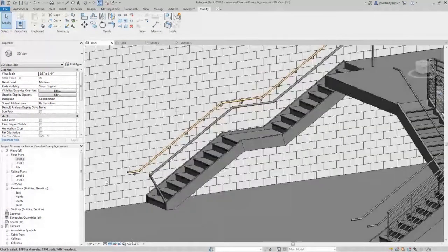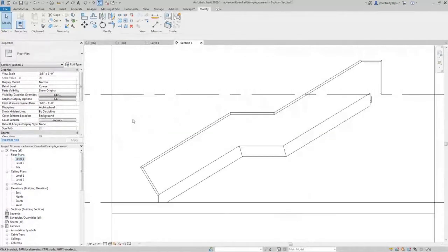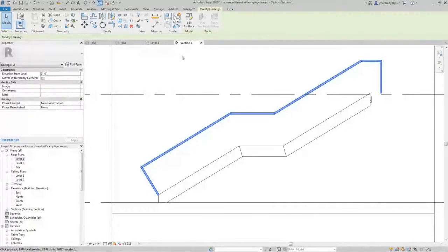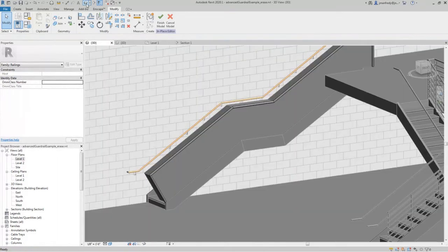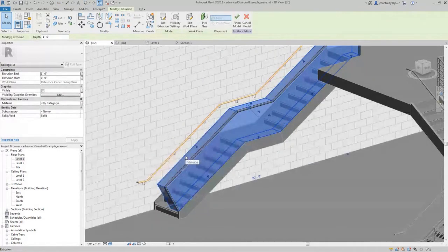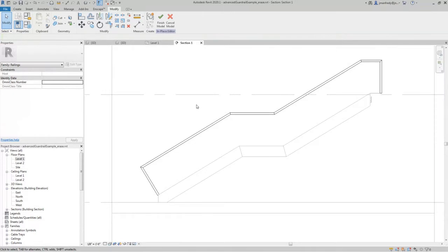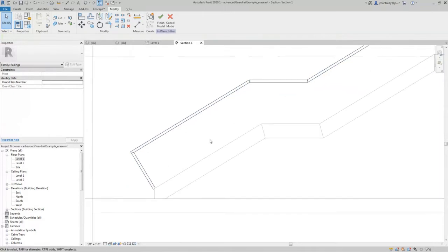I go back to plan view, I double click here, I click on this object, edit in place, and it'll bring them both back. All right, it'll bring them both back because this is no longer invisible. I'm inside the family. That edit in place model, I'm inside there, working. So now I can continue doing my business here.